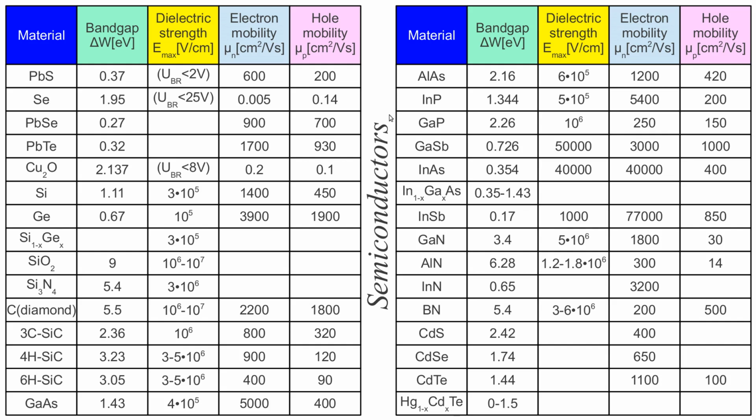Similarly to the band gap, also the dielectric strength of an intrinsic, so not doped, material follows mainly the band gap of the semiconductor. So usually materials with a low band gap have a poor dielectric strength. Materials with a wide band gap, like gallium nitride, have a very high dielectric strength.